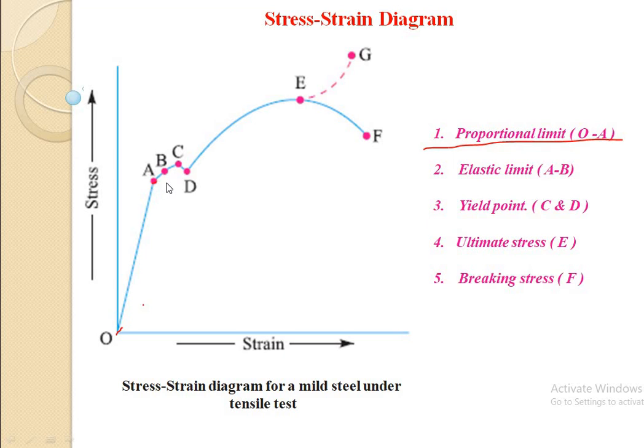Now, just concentrate on point B. Beyond point B, the strain increases at a faster rate with any increase in stress, until the point C is reached.